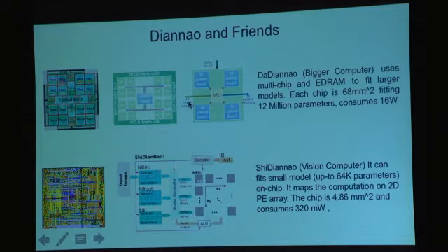And what they did here is realize that they were limited by their memory and chose to put a bunch of memory on their component. So they have embedded DRAM on this part. The part is basically a big memory chip. These are all the memory components, and it's tiled. So you have some of the memory and then a compute unit for each of these tiles, and the function unit basically sits in the middle of each of them.